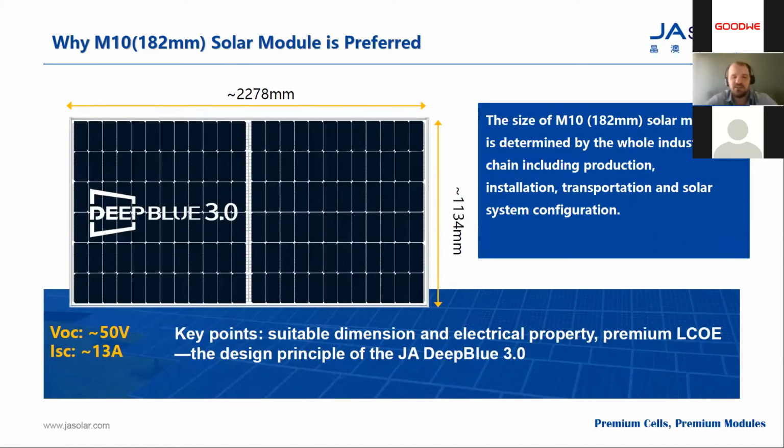So as I was saying, the 182 millimeter cell is typically more preferred in the African market at this stage. If you're considering it from an installation point of view, higher kilowatt peak rating can fit in a container, so it accounts for lesser cost shipping. Installation is essentially quicker, there's less cabling needed. The modules themselves are relatively large, so they do require 2 people to carry one, for example. But if you're taking the overall cost of the balance of system, it does work out cheaper in the long run to look at a higher power class